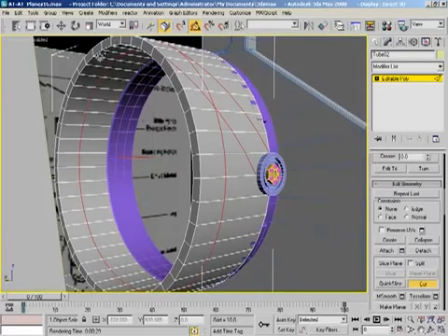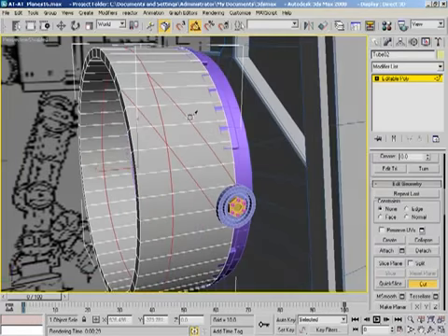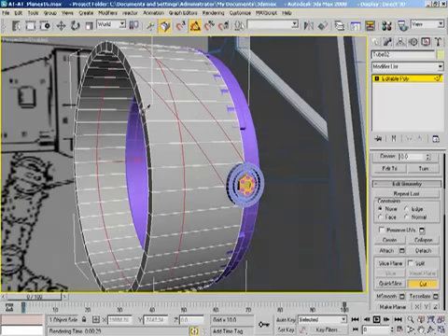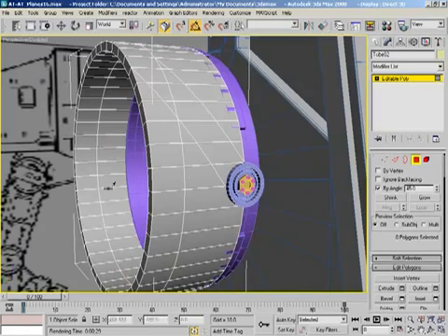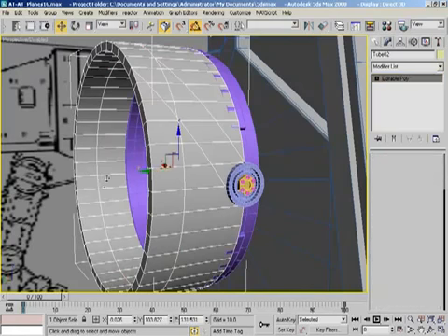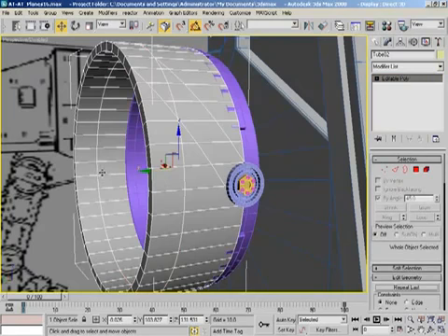In the end, it doesn't look like we're going to end up using this tube. I'll just cut everything else out and remove our thickness and then extrude it back in to regain our thickness. So let's do that real quick. Let's grab 4 to get faces. Let's select by angle 45 degrees and get out of the cut tool. And let's see here.